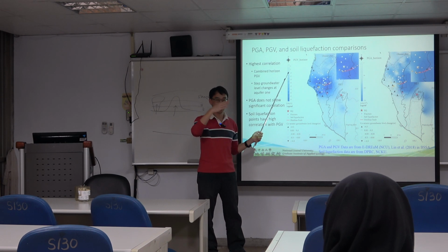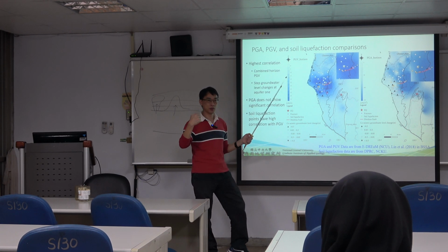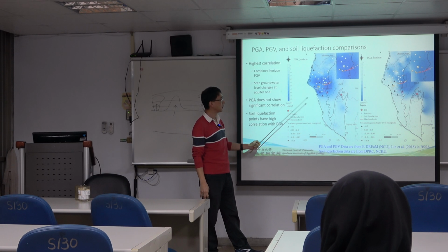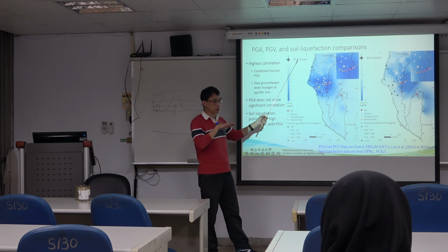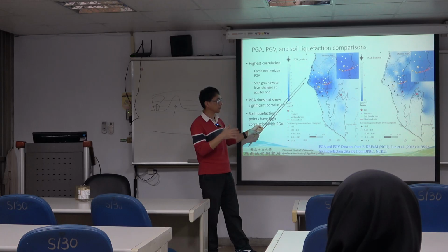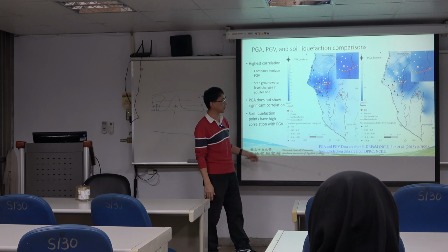We can do the integrations to go from acceleration to velocity. We can have the velocity field, and we can also get the maximum point to have the PGV. And there's horizontal, which means we combine the north, west, and southeast components, so we try to combine the components together to be the horizontal PGA and PGV.